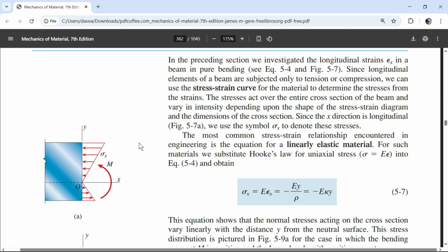So when we do have a specimen and we load it, if I have a 1 inch by 1 inch steel bar, and I put a tension on it of 58,000 pounds, the surface area is 1 square inch. The load is 58,000. The pressure I'm putting on that cross section is 58,000 psi. So that's this term, and that's the max I can put on it. If that bar is 1 meter long, I'm going to see a lengthening of 2 millimeters. So that's 2 divided by 1,000, which is 0.002. So I put 58,000 on this side and 0.002 on this side.